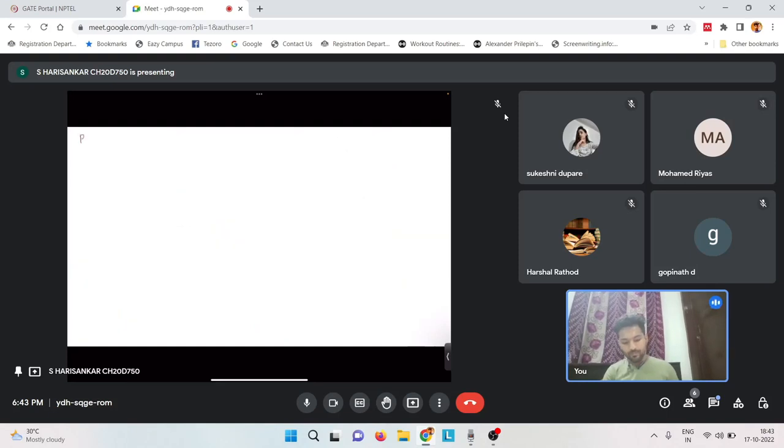Okay, fine. Now, what if we looked at CSTR in series now? Let's look at PFR in series. Let's take a PFR like this, which has a space-time of tau 1 and a volume of V1. We have another PFR like this, which has a space-time of tau 2 and a volume of V2, and so on up to n PFRs. You know the design equation for PFR, right?